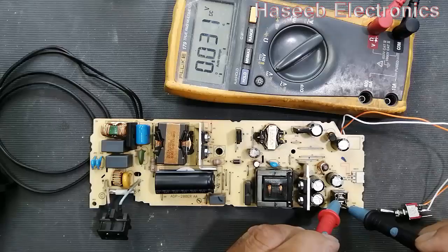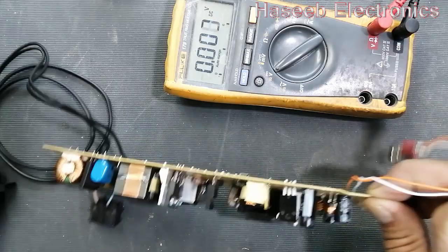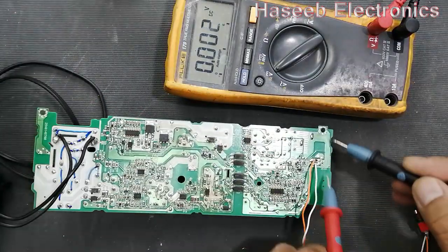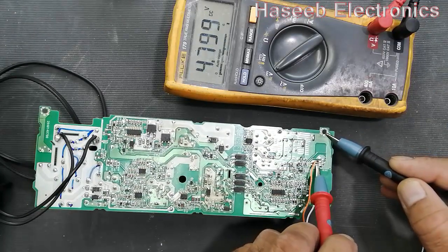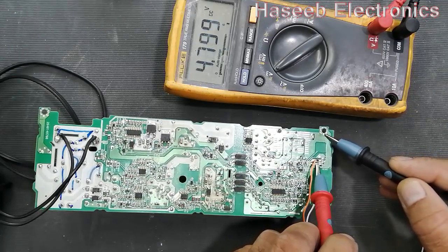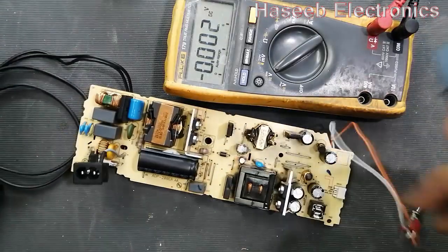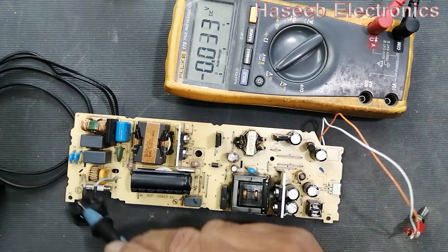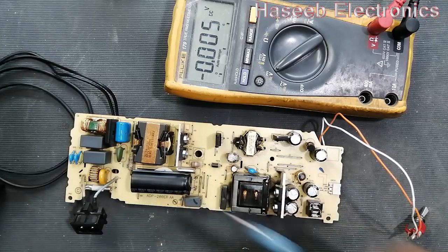As per our calculation, the output of the bridge rectifier is okay, 331 volts. No power at output, and we are just taking the standby voltage, at this point and this point, 4.8 volts. That is the standard output of this power supply from this small section. I discussed this section already, and I discussed the DC rail circuit and input protection circuit in our last video.